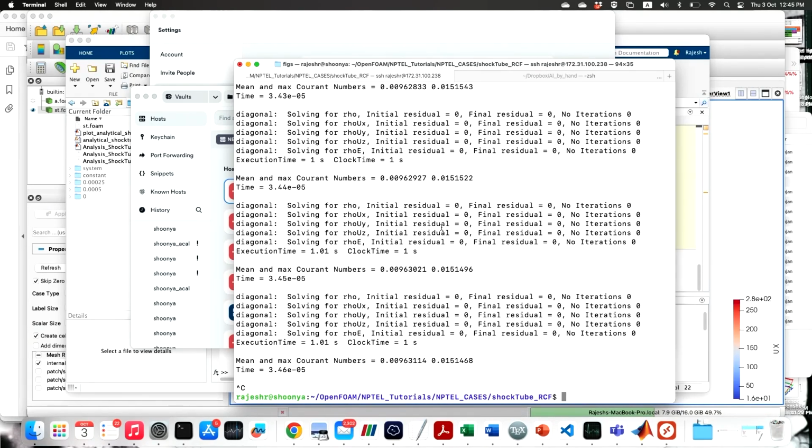Okay, so this is a density based solver, unlike sonicFoam, which is a pressure based solver. So there we saw that we are solving for Ux, Uy, Uz, and then p and e, right. Here you can see it is a solver that we have been discussing a lot in our course, right. You are solving for rho, which is the continuity equation, and rho Ux, rho Uy, rho Uz. Okay, so it is solving in the conserved manner. Okay, and finally the rho E, right. So it is solving for all 5.